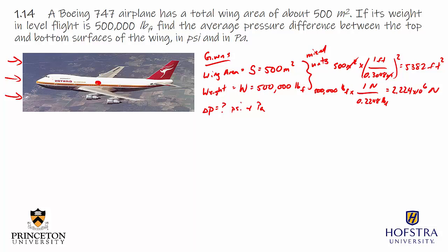Well, the first thing is that the aircraft has some weight down, W, and the engines would be producing some thrust force forward, just call that T. And then the flow going over that is going to create some aerodynamic forces. We typically break that down into a lift force, which is vertical or perpendicular to the free stream velocity, and one which is parallel, which we typically call the drag force.